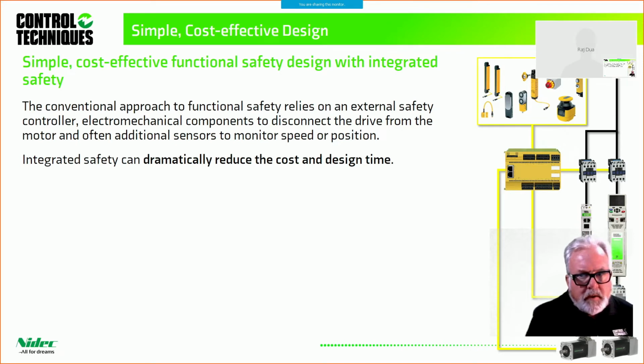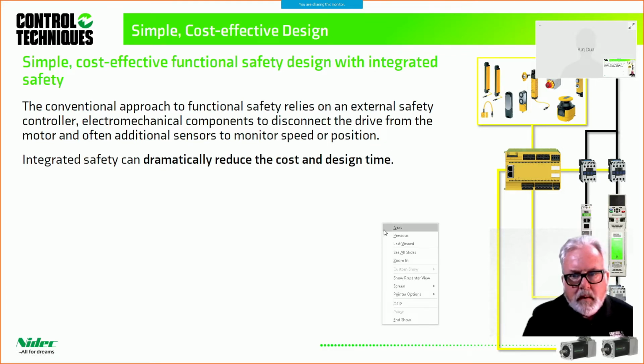So the design now. The conventional approach to functional safety relies on an external safety controller that you see here. Let me get my pointer fired up here. So here you see there's a traditional safety controller, safety PLC. And you see that we have a couple of drives here being powered from the mains, and there's contactors on the input and contactors on the output side of the drive.